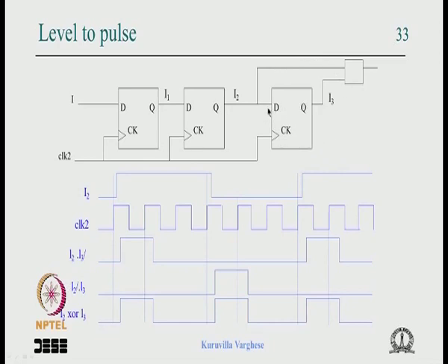Now this is where all the transformation happens. We have an input, a flip flop, its input and output is combined through a logic, and assume that logic is I2 and I3 bar. So you assume an AND gate here, I2 goes straight to the AND gate, I3 goes through a bubble or an inverter, I3 is inverted, see what happens. So assume that this is the clock to the state machine, which we use in the same transformation circuit, and see the I2 goes like this.